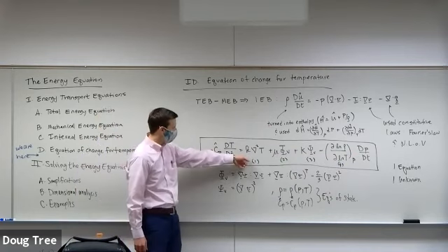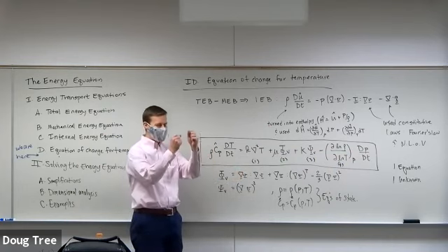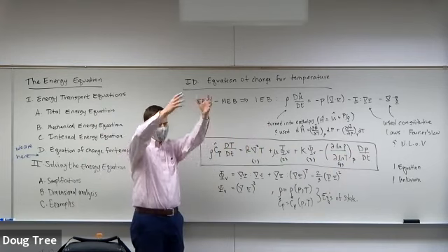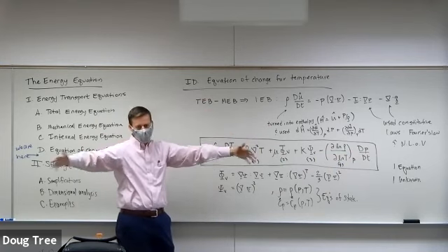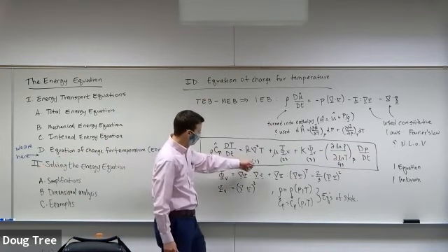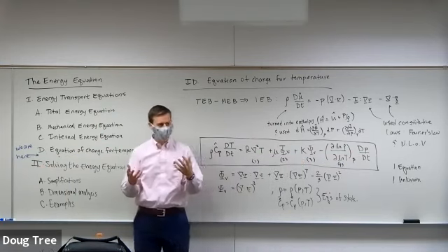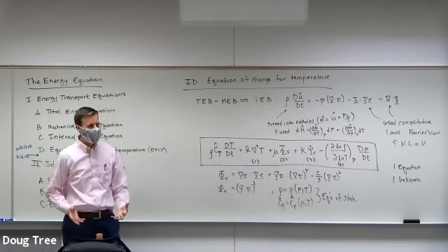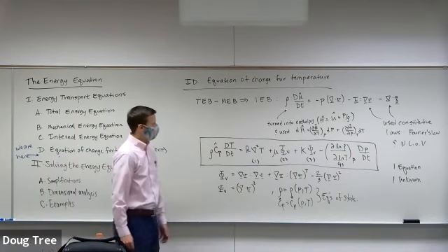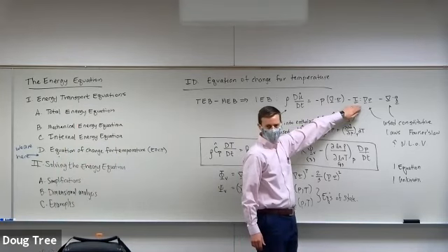So the first one here is thermal diffusion, or conduction. If I have a temperature somewhere high and low temperature elsewhere, temperature is gonna want to spread out and tend to be even. That's what that term wants to do. These 2 terms, 2 and 3, are source terms for the temperature. So they're adding heat to the system, and they come from this viscous dissipation term up here, this tau double dot grad V.